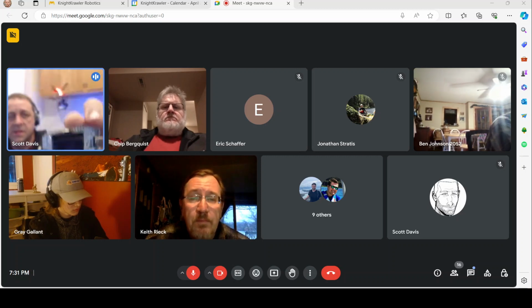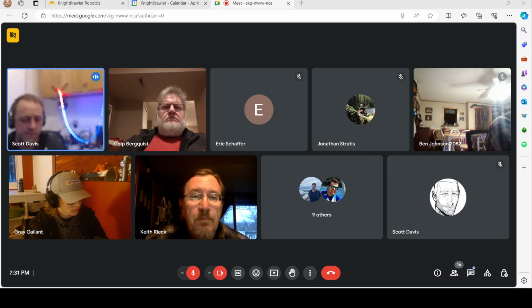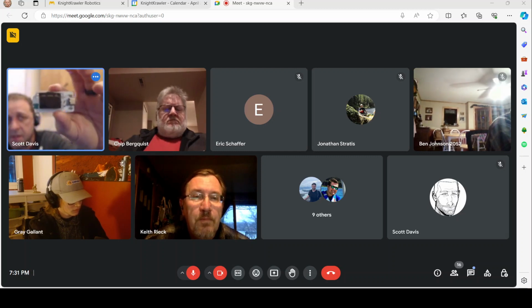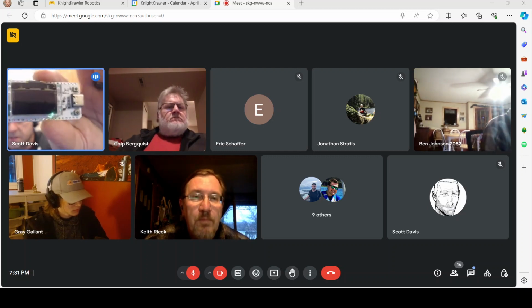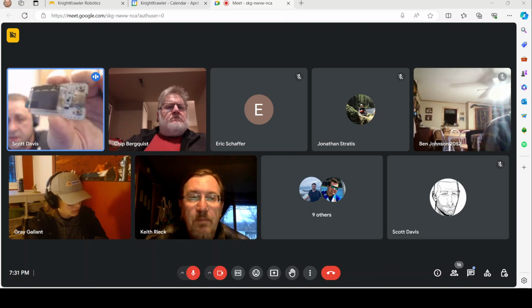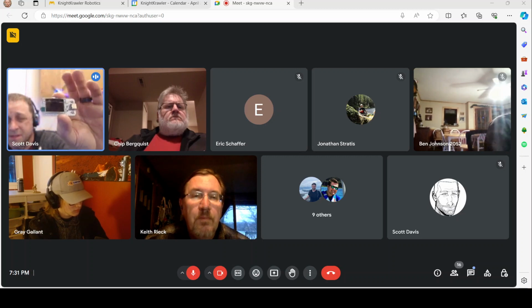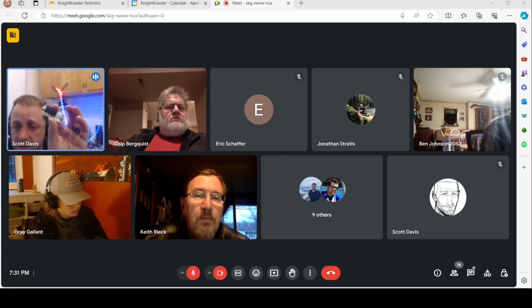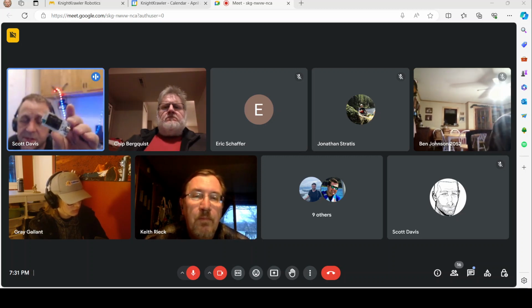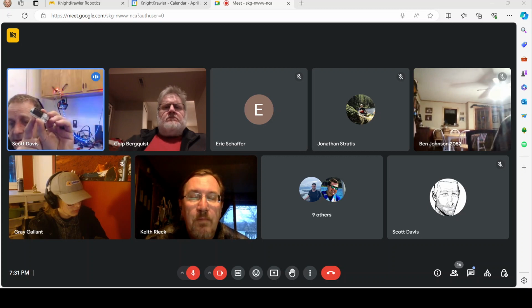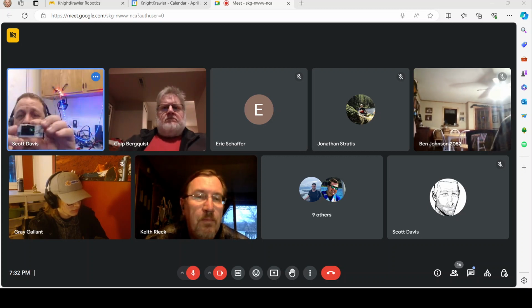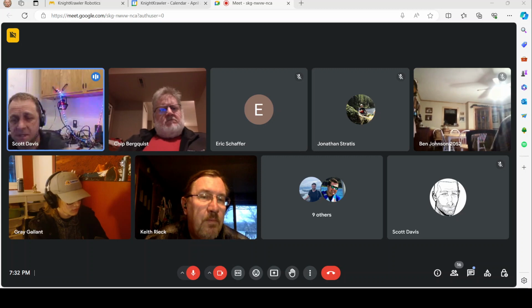The problem is that this screen is communicated with I2C. A lot of these little OLED screens that you can get for Arduino are I2C screens. And I'm pretty sure it's a software implementation of I2C instead of connecting to the clock and the data pins that are right on the chip. Because of that, the update is really slow.